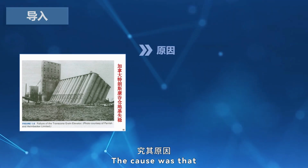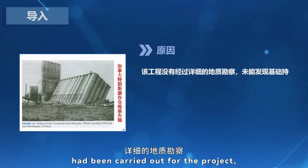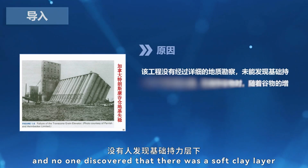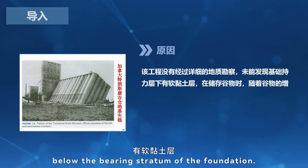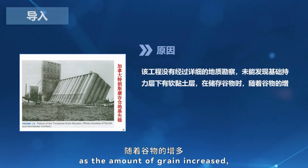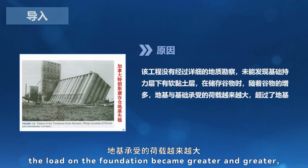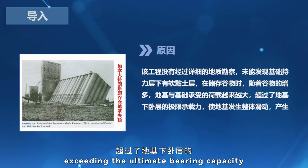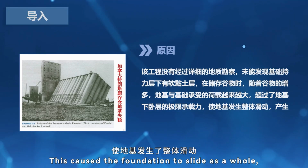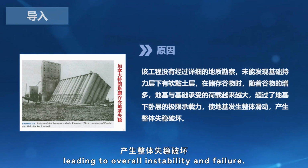The cause was that no detailed geological survey had been carried out for the project, and no one discovered that there was a soft clay layer below the bearing stratum of the foundation. When storing grain, as the amount of grain increased, the load on the foundation became greater and greater, exceeding the ultimate bearing capacity of the underlying layer. This caused the foundation to slide as a whole, leading to overall instability and failure.